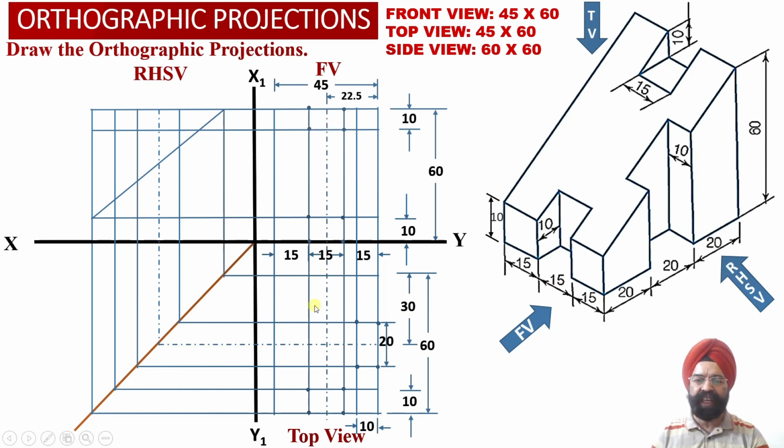How do we evaluate the depth over here? Now we can check. As we had drawn a horizontal projector line through this point, because I want to determine the distance of this edge from the rear face of the solid. This is the rear face of the solid. I want to measure this dimension over here. Now we can use the orthographic projection principles in order to evaluate this depth of the top surface horizontal slot over here.